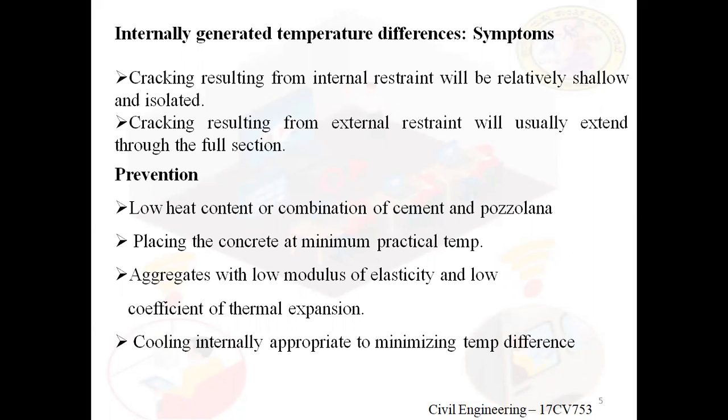So some of the symptoms with respect to internally generated temperature: the cracking resulting from internal resistance will be relatively shallow and isolated, because if there is temperature variation inside the structural elements, small cracks will develop, and they are only shallow and isolated. For example, where the temperature is more, there the cracks will develop. Where there is less temperature, there the cracks are not there. So these are the main symptoms of internally generated temperature differences.